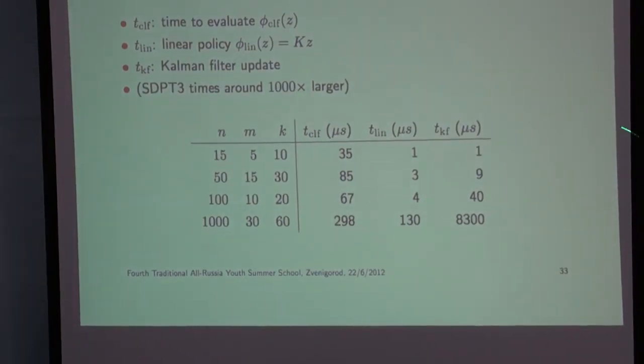So these are some systems here. Let's take here's a system with 50 states. That's probably bigger than you would ever control. 50 states, 15 inputs, 30 inequalities, and I think the inequalities are just limits on the input. I'm sure because that's twice that. So, and let's see. How long does it take to solve that? Again, that's also out of date, but it doesn't matter. That's 85 microseconds. Okay? And I don't give you the CVX times here. They're typically 1,000 to 10,000 times slower. Okay? So I think these numbers change everything.